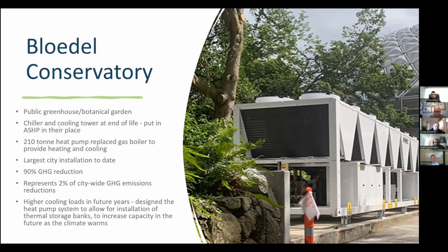So in this case, the unit goes into defrost, and that's been a little bit of a challenge with this project. We were actually expecting that half the unit could go into defrost while the other half would keep going heating the building, but it turns out that we didn't order it that way, so the whole unit goes into defrost. So what we've done is just increase the loop temperature to try to keep it being able to heat the building while it's in defrost. But anyways, it's been a very successful project.